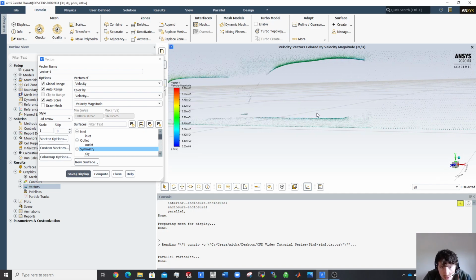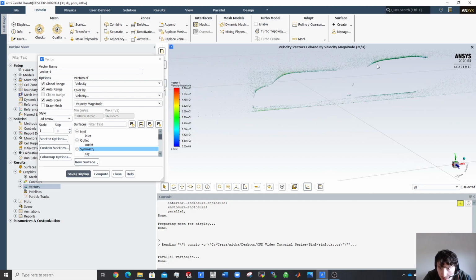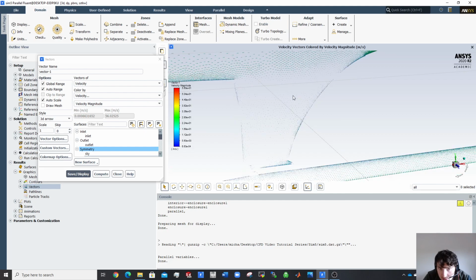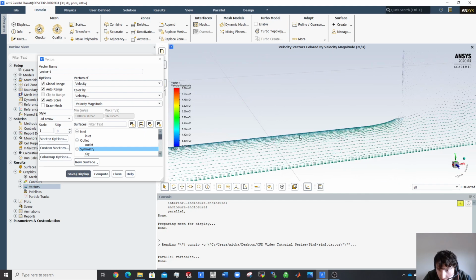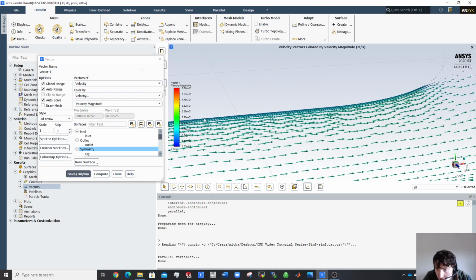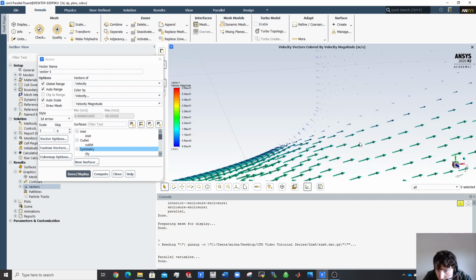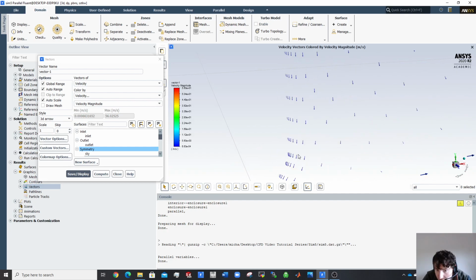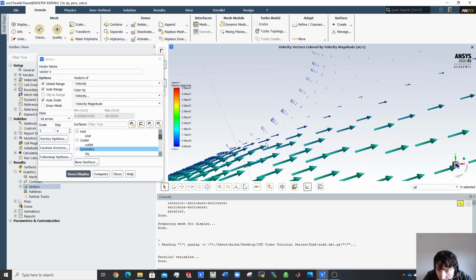This is what we're looking at here. You can rescale these vectors, but it's just showing you regions where the flow might be moving very quickly. You can see the vectors are very small in there, so there isn't much flow movement. This describes another way of evaluating the performance of something like a diffuser. You can see how the flow goes, and you can see most of it shoots off this way. Very little of it comes off at that angle, and very small amounts are getting pushed back down here. You can see the bit of recirculation starting to happen and starting to push this flow off.